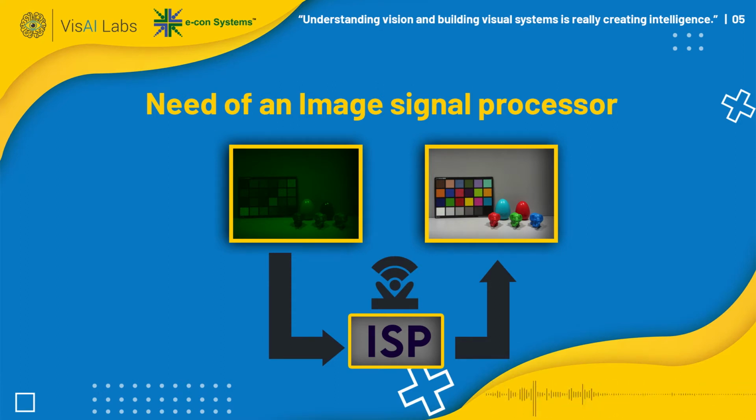If it is a monochrome sensor, we may not need a full-fledged ISP. All we need is just an auto exposure, which can be handled in the software, or some of these monochrome cameras come with an auto exposure inbuilt. But if it is a color camera, ISP is a must. And mostly, choosing an ISP is the most underrated thing. We underestimate the time consumption of integrating an ISP with a sensor, but fine-tuning an ISP is the most time-consuming work in the product development cycle.